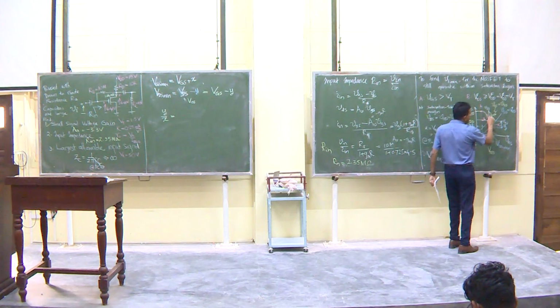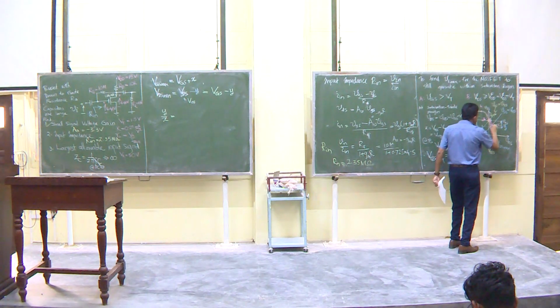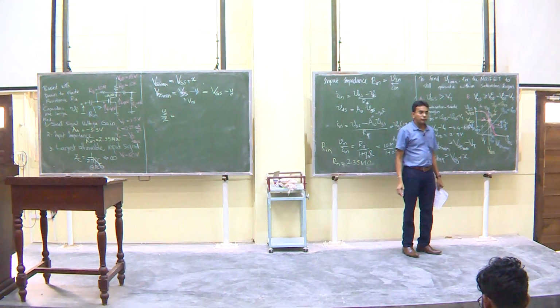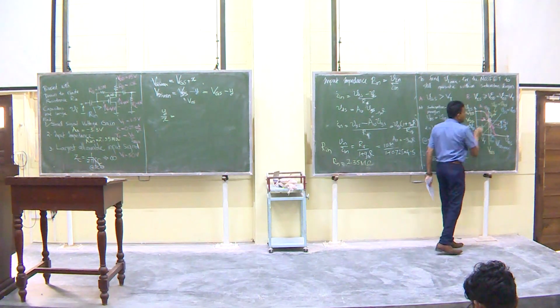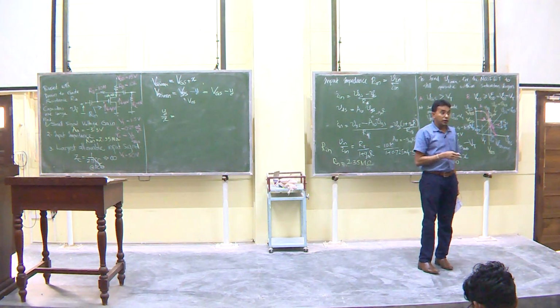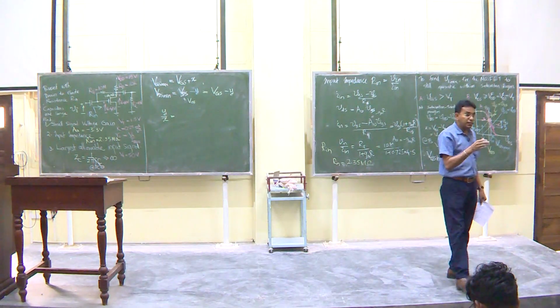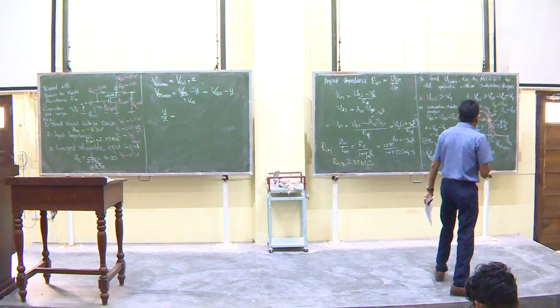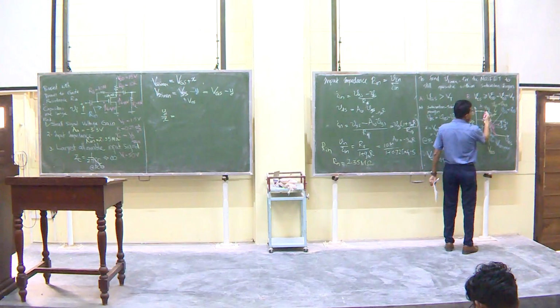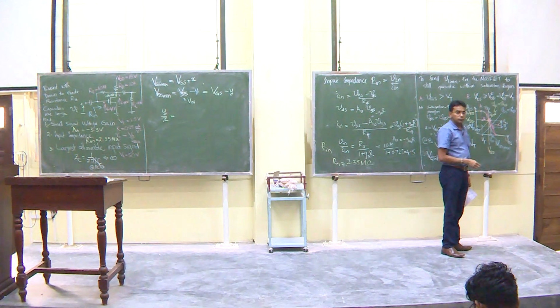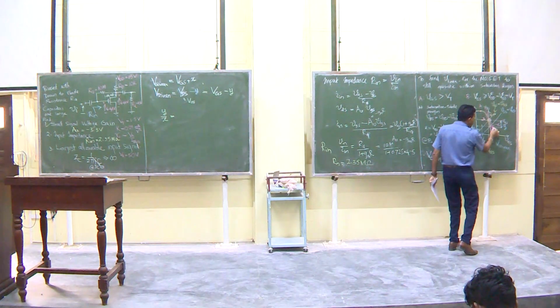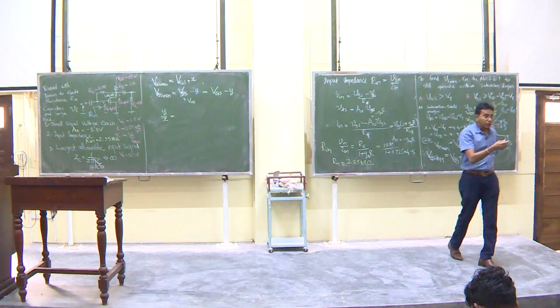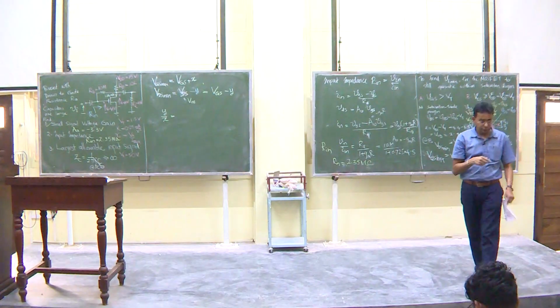So, if I draw a slope here, like that, through that operating point, that's the curve that defines the VGS to VDS relationship, correct? That is the gain. So, therefore, the slope of this is what defines its gain, right.